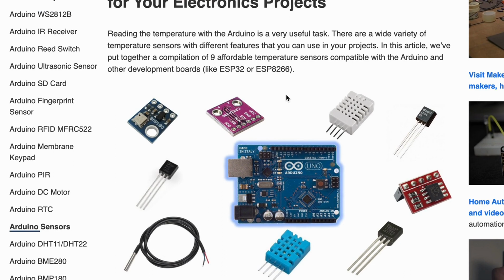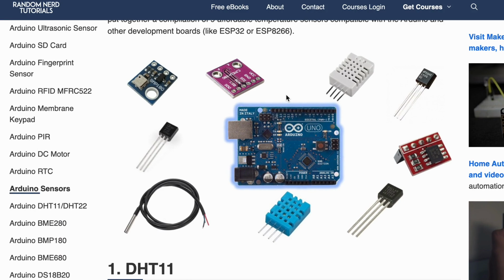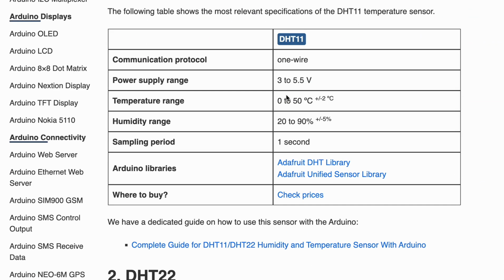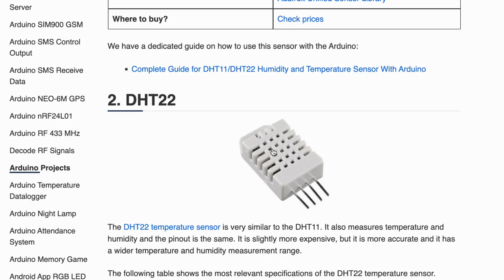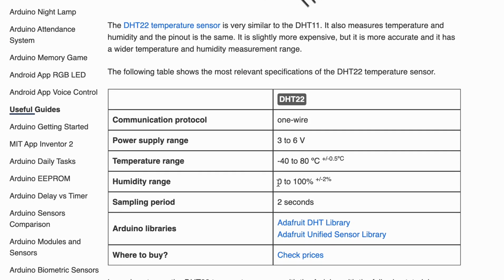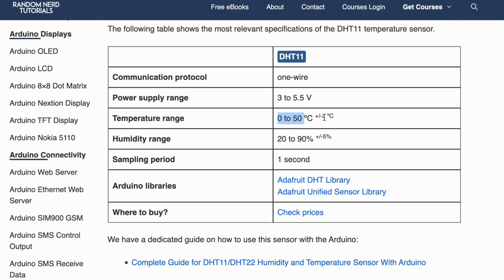Then you must also see, when we recognize we want to measure the temperature, what ranges the sensor itself covers, and what errors will be given when approximately measuring these things, right? So for example, you can see here it's a 2-degree difference.